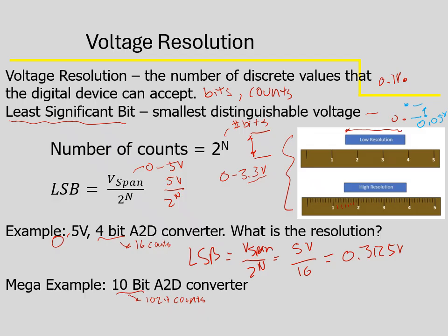On here, 10-bit. The Arduino Mega has a built-in 10-bit A to D converter. That's really nice, but 10-bit really isn't that great. If we're measuring something with a 0 to 5 volt range, we've got a resolution of 4.88 millivolts.